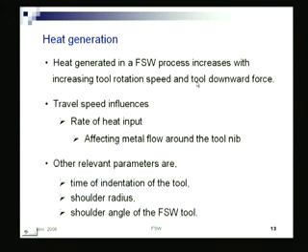So then we come to see how the heat is generated and how it is quantified in this. So heat generated in the FSW process increases, as we have already said, with increasing tool rotational speed as well as downward force. The simple reason, as the downward force increases, your frictional force increases.